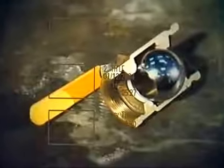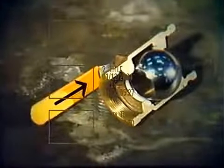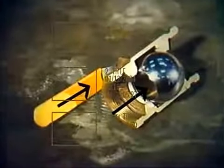In a regular on-off ball or plug valve, the handle is usually in line with the post. So if the handle is lined up with the pipe, there will be flow through it. This is a butterfly valve. Now, these valves are normally found in low-pressure, low-temperature systems. Butterfly valves are useful on large volume systems where space is limited.